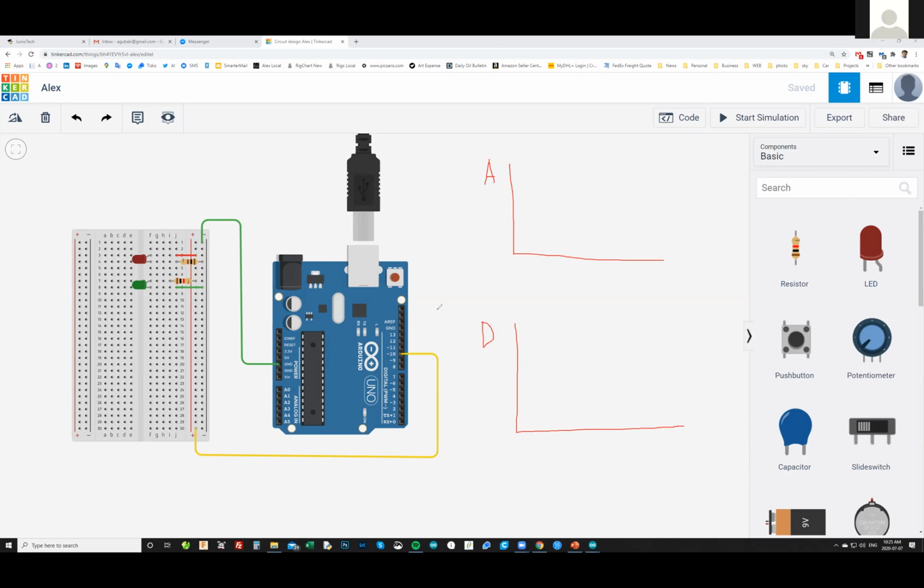Okay, so, Alex, before you move on, I just want to quickly recap. After you connect your board, the next thing you need to think about is which code you're pushing onto the Arduino, and whether you connected it to a digital or analog pin. As Alex said, all those 13 pins are digital. That's where we connect LEDs. But he's going to introduce you to the concept of analog pins today, because those are used to connect the sensors, and those start with the letter A.